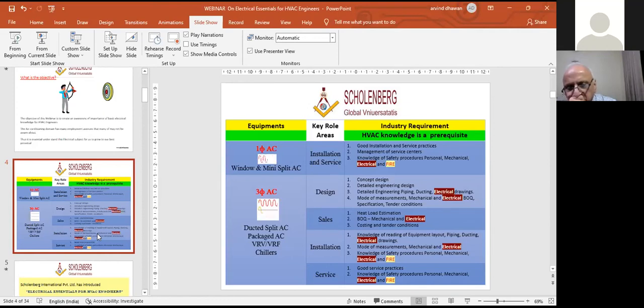Now you are questioning, do we need a harmonic filter? See, the harmonic filter comes into the picture when you are generating a large amount of harmonics. Large amounts of harmonics are not generated at the pumps for the HVAC plant, not even the AHU. It is generated mainly at the chiller part. And now the majority of these chiller manufacturers are smart enough to take care of it in their own control panel. But again, when the plant capacity goes to 500 tons and above for each chiller, and you're running multiple chillers, then